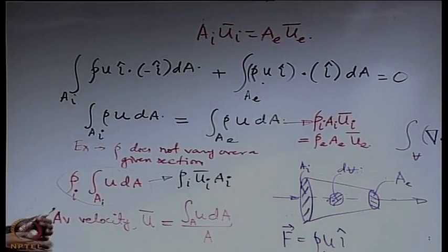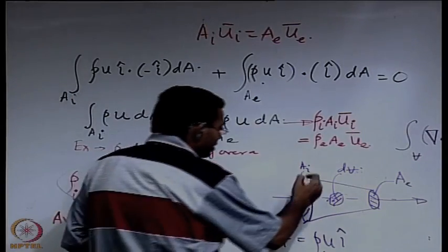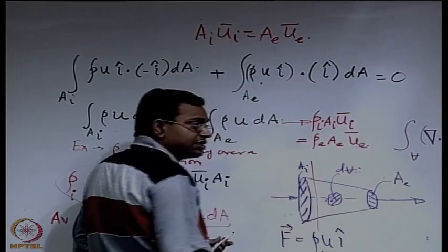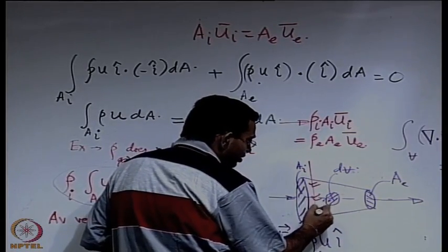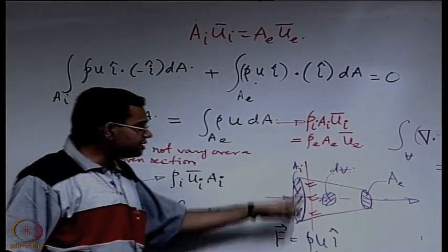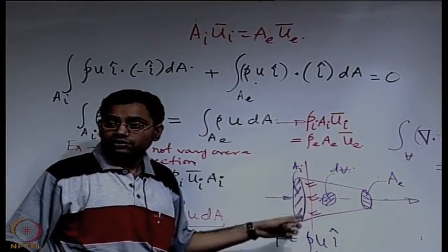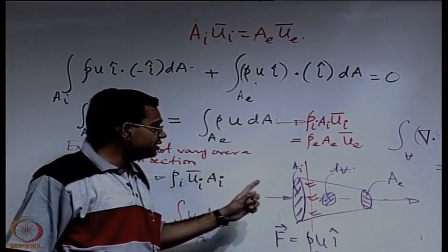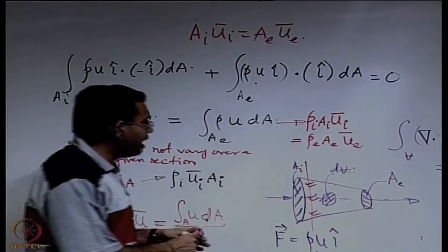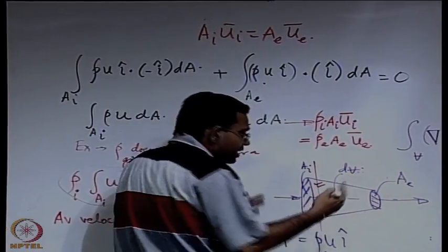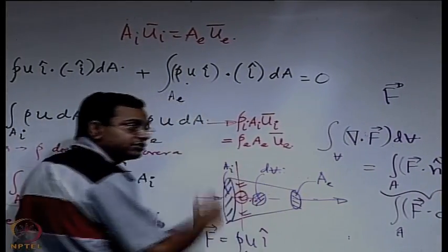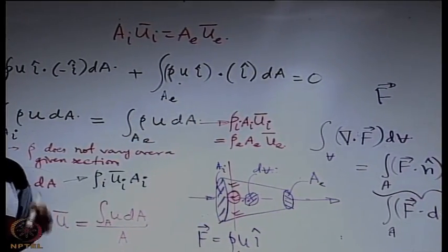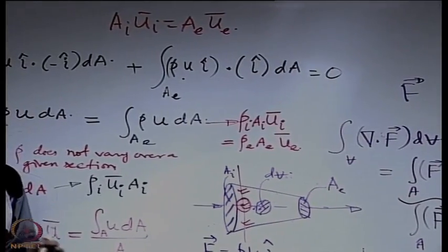So if you consider a cross section like this, now let us identify 3 different points, say these 3 different locations. At these 3 different locations the velocities are different. So when you write, say, ρ U_i U bar, maybe sometimes in your previous studies you have written it as the velocity at this point, right? Fundamentally that is incorrect, that is wrong.